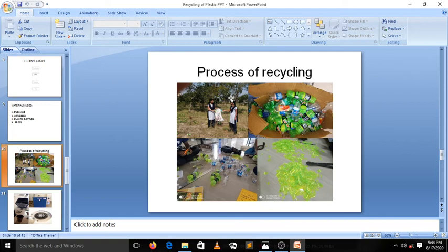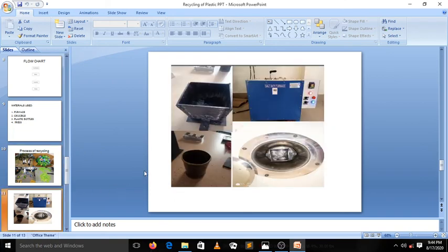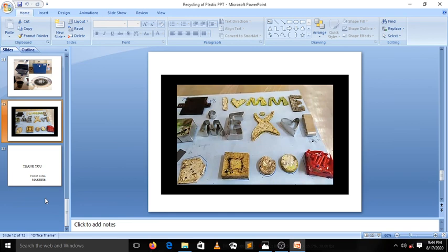Firstly, I collected the waste bottles on our campus, and here you can see the students collecting the waste bottles. Then the bottles are chipped into small pieces. Then the chipped pieces are kept into the mold, which means a steel barrel. This barrel is kept into the furnace, and we apply the softening temperature. After that, we take out the barrel and do compaction.